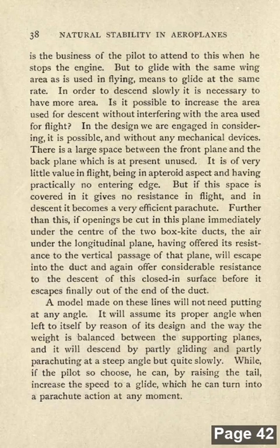the air under the longitudinal plane, having offered its resistance to the vertical passage of that plane, will escape into the duct and again offer considerable resistance to the descent of this closed-in surface before it escapes finally out of the duct. A model made on these lines will not need putting at an angle. It will assume its proper angle when left to itself by reason of its design and, though weight is balanced between the supporting planes, it will descend by partly gliding and partly parachuting at a steep angle but quite slowly. While, if the pilot so choose, he can, by raising the tail, increase the speed to glide, which can turn into a parachutation at any moment.